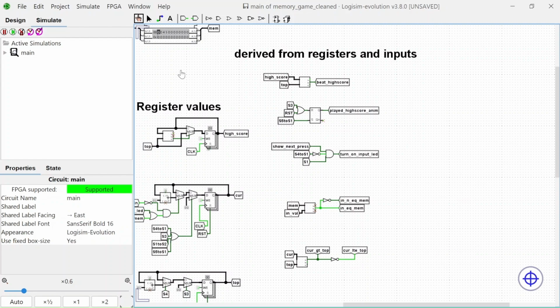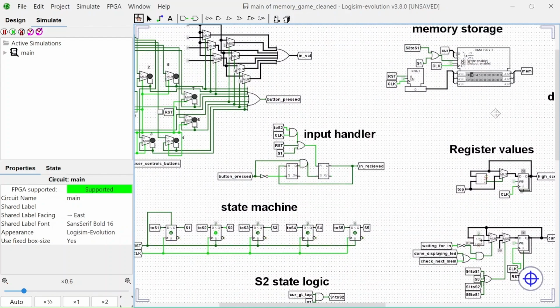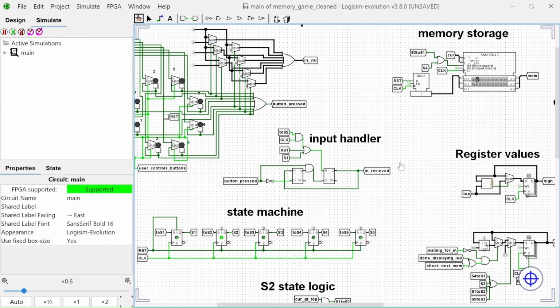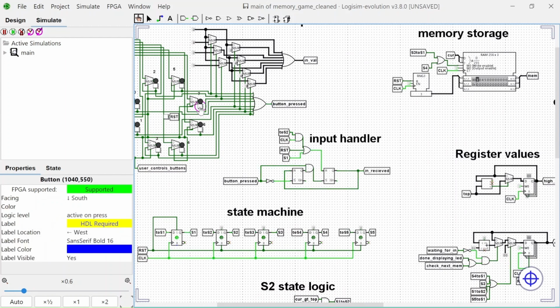This system stops button presses from glitching out. It converts asynchronous input to a synchronous signal. I started this project before I knew how to make a good edge detector with one flip-flop, so I used 2 latches and a bunch of other logic. And this would not be good. This probably would be bad for metastability.